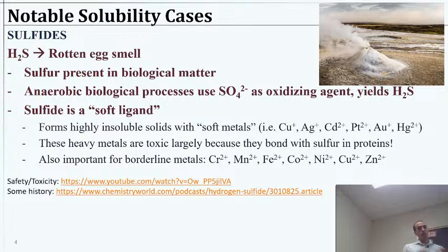Sulfur is an important component of all biological matter because it's part of DNA, part of proteins, things like that. It's not in a huge quantity, but it's there. And so if you have sulfur and an anaerobic process, a biological process decomposing stuff, you're going to end up having bacteria that use the sulfate as a source of oxygen or an oxidizer, and that's going to generate hydrogen sulfide, H2S.